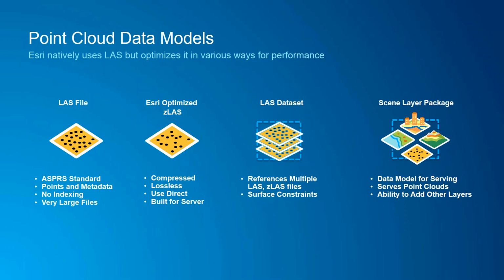First thing that I definitely want to point out is that Pro now can natively read a LAS file. So you can simply drag and drop a LAS file right into your screen, and then you'll be able to bring it up, visualize it, do measurement, and do different types of analysis directly on the file. It used to be that you would have to have a LAS data set in order to be able to do that. That is no longer the case.